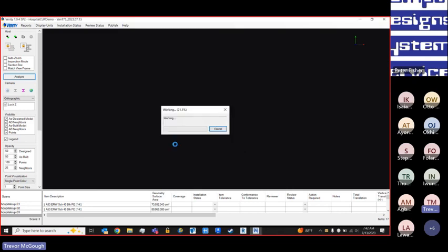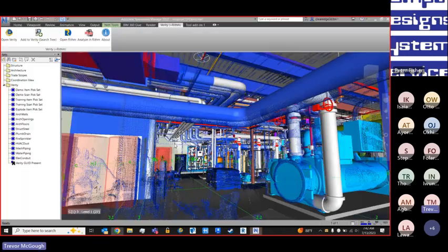When I click OK, Verity is going to go through and say, is the geometry found within the point cloud, i.e., has it been built? If it's not, it'll flag it as missing. If it is built and it does find it, it'll say, is this piece of geometry inside of tolerance? If it's in tolerance, good, great, well done. If it's out of tolerance, Verity will create a copy of the geometry, and that copy it'll refit back to the point cloud to show you the true as-built location of what should be there.